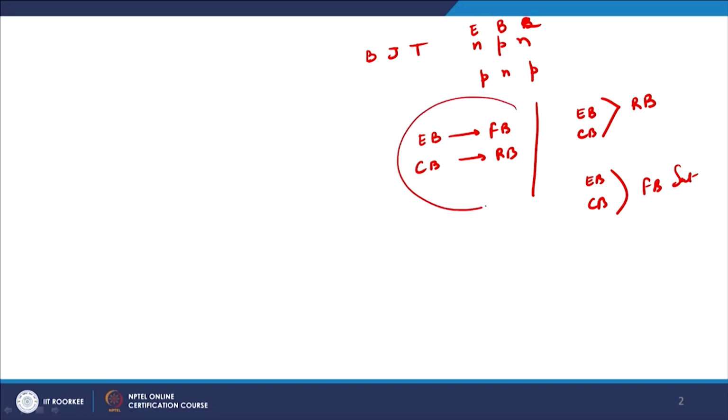So, typically this is where we define the on state and we get a better idea, right. Please understand, when you want to move the BJT from a saturated state to a non-saturated state, you spend a large amount of time in switching, because the charges in the base have to be removed or flushed out before the next cycle starts. So, the time taken is very important. We will see in a differential amplifier that we do not like the devices to go into the saturation region, and that is the beauty of the whole thing, that it gives you a much better gain, and not only gain, it gives you much faster switching speeds.